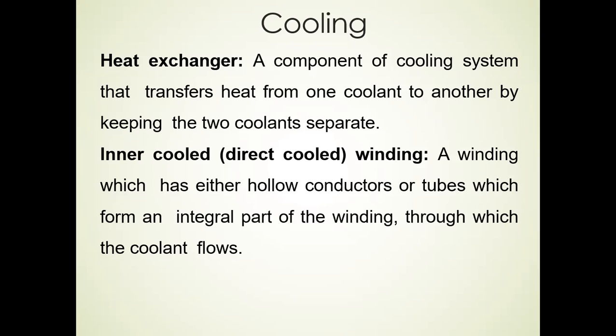The heat exchanger is a component of cooling system that transfers heat from one coolant to another by keeping the two coolants separate. Then what is inner cooled winding? That is direct cooled. A winding which has either hollow conductors or tube which form an integral part of the winding through which the coolant flows. So the terms and definitions about the coolant system is very important. So we have primary coolant, secondary cooling, heat exchanger, and inner direct cooled winding.